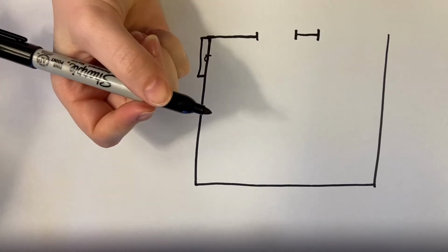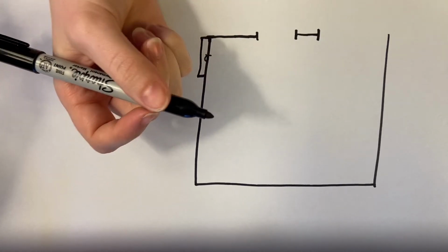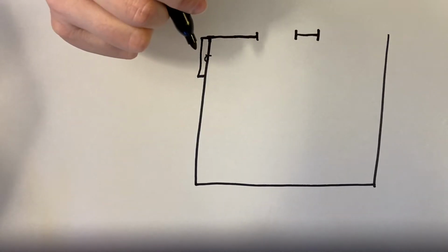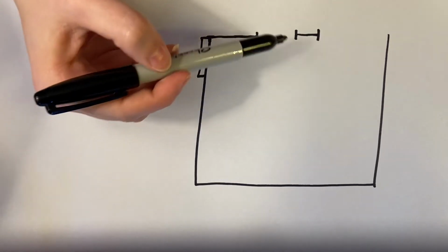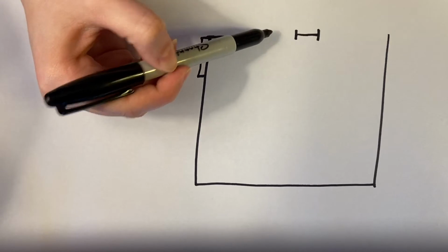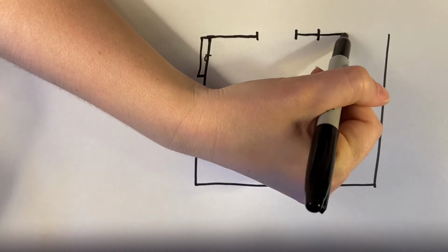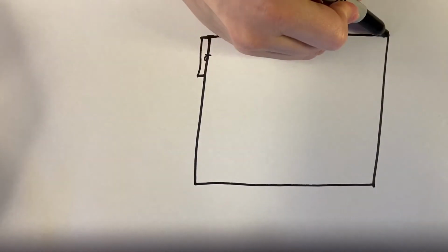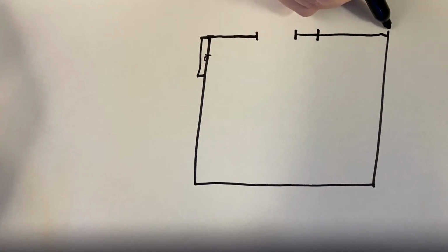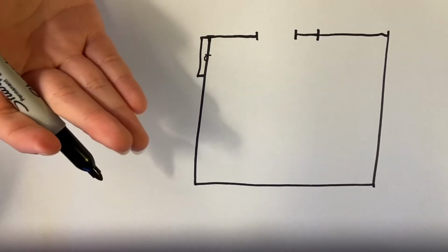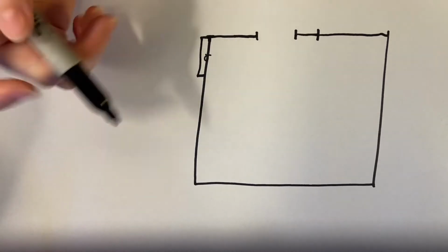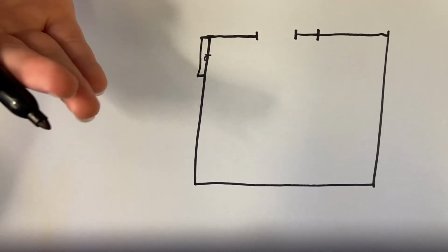I have a pass-through in my kitchen. It's literally a hole in the wall, a finished hole in the wall that opens through to my kitchen. And so to notate that, to make it clear that it's not a full opening like this, I'm just gonna continue that line. But the little tick mark that I have here and here really just shows that there is something different about that. So even if it's not clear and you forget to make note of it, I'm gonna see something like that and be able to make a change.